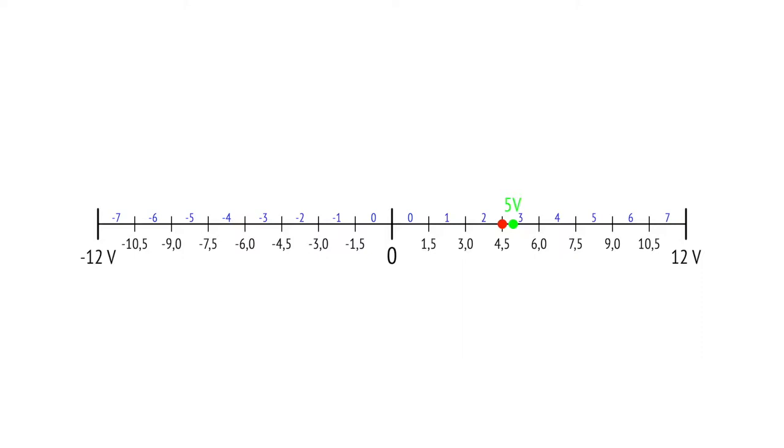If converter returns the half of width levels, then we get 5.25 volts, but it also is not 5. This example showed to you that inside one stripe I am not able to distinguish the real measured value. We just know that it is inside this stripe. It means that all possible values inside one stripe are converted to the same stripe number.